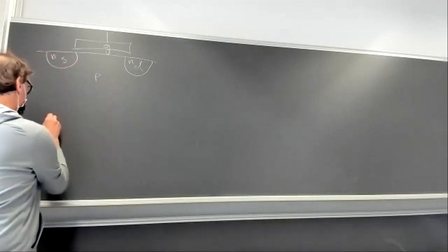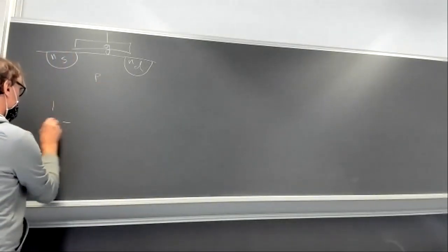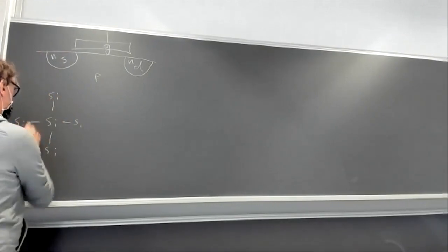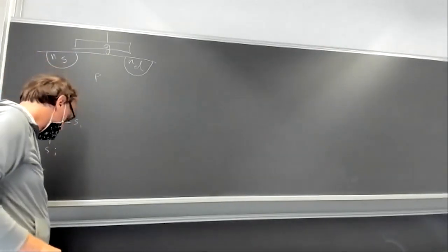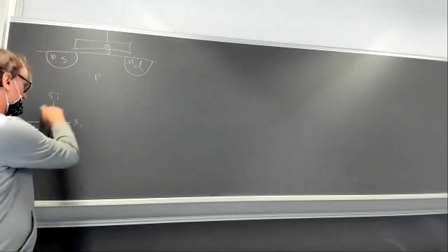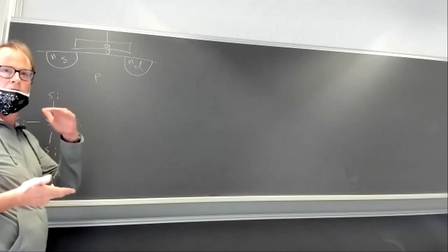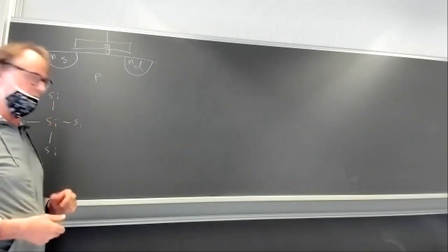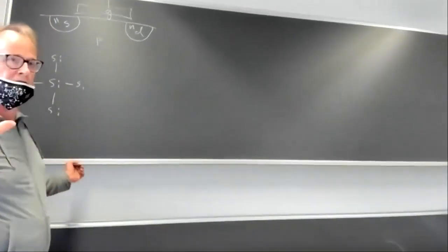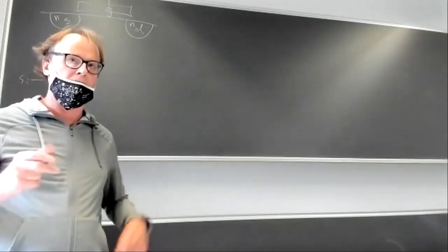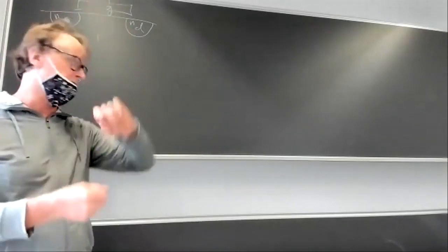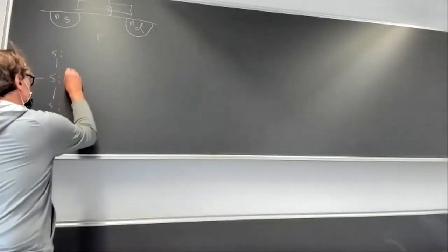That's because you take the silicon atom and it's joined mostly to other silicon atoms in this crystal lattice through the 4 outermost electrons. And the silicon atom will give up its outermost electrons here with about 1 electron volt worth of energy. It takes about 1 electron volt worth of energy to break one of these electrons free, normally. And since the thermal energy is only about 1/40th of an electron volt, the average energy of vibration is about 1/40th of 1 electron volt. It's a tiny fraction of this band gap energy of 1 eV to get it loose.